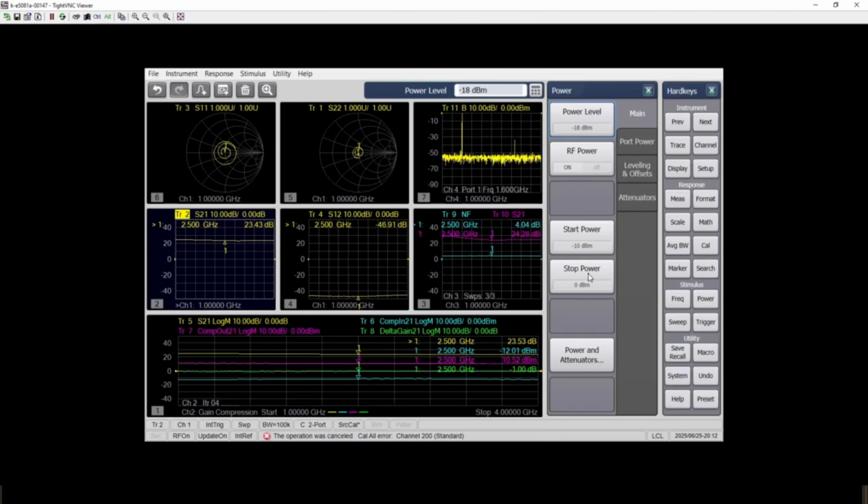So that's it. This is the setup, so you can combine multiple measurements in different channels and then put all on the screen, and just one calibration step covers every different setup, and then you can just plug in your device under test and do the measurements in one go.